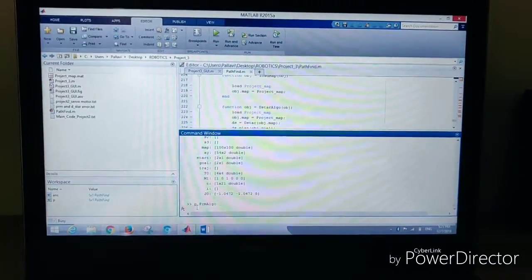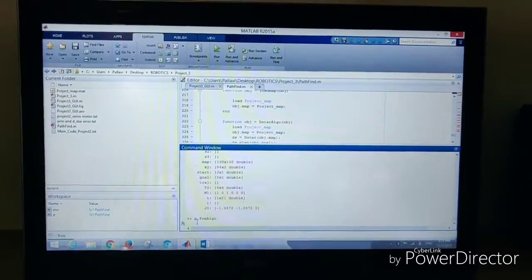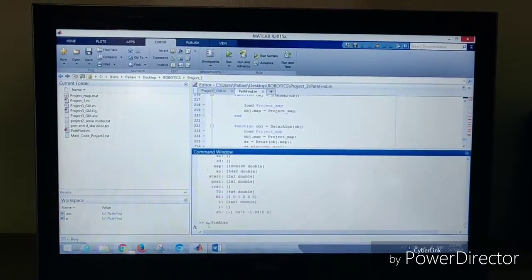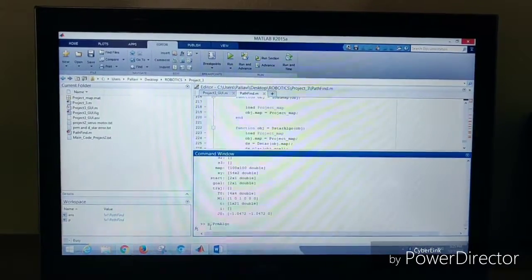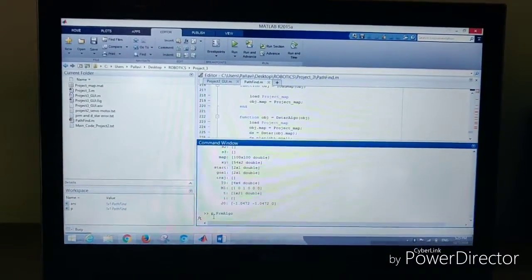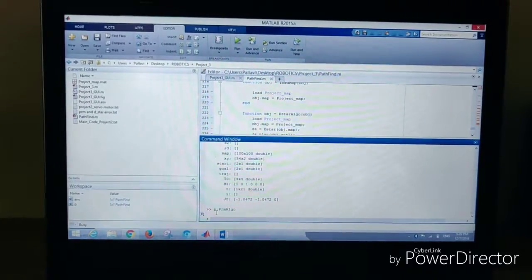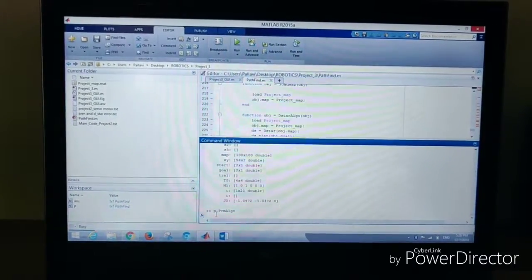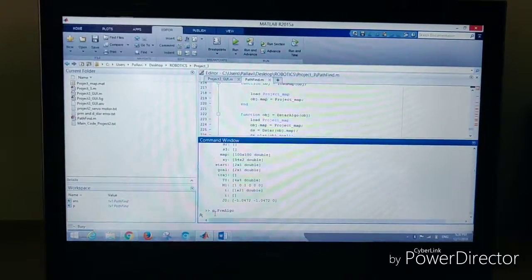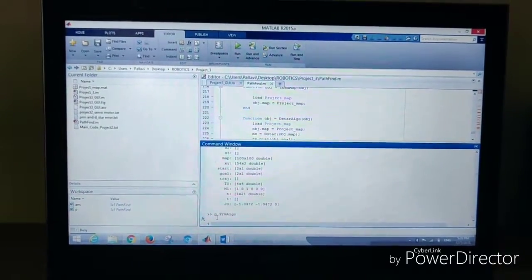Our next algorithm is the PRM algorithm, which is faster than the D-star algorithm because it is made of different nodes. We are using 300 nodes in this map, so it will find the proper path, avoiding the longer routes and achieving shorter ones. It will search for the goal and start positions based on our inputs, whatever maze we select, or whatever goal positions we choose in the GUI. I'm going to show you.